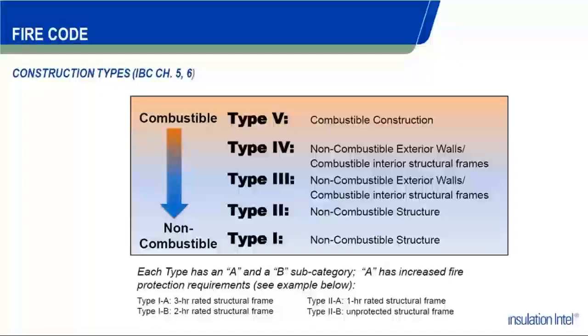So looking at fire codes, just addressing some of the concerns on fire codes. Generally speaking, the NFPA 285 is one of the more recent concerns in the market, and it's triggered when you try to use a combustible material in a building that requires non-combustible exterior types, and this really doesn't matter what construction type you're categorizing your structure as, it really does apply to all types.